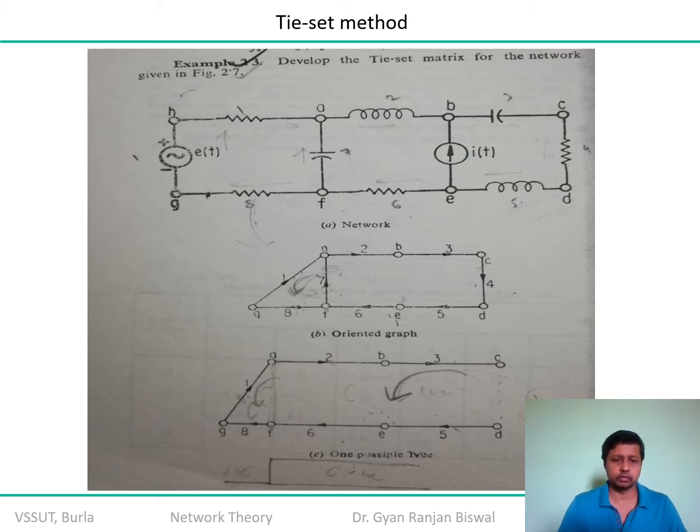So for example, if I am going to demonstrate over here, and you want to interconnect this point, that is your G and H. Okay, so this G and H is going to be replaced by a line. Let's say if this is the point and this is another node, or you can say that this particular node is G and this particular node is H. Okay, and I would say that this particular node is A. So remember, because of this voltage source, these two nodes will be short circuited, and H and A consist of one element, so this node is finally going to be interconnected with A.